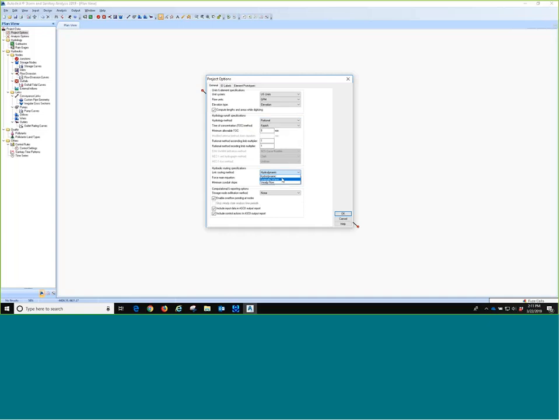So I'm not going to get into too much detail into the differences between them, but know that the hydrodynamic is actually the St. Venant equation, so it's the one we're going to use for our pressure network and our lift station design, because it's the only one that can do reverse slopes, whereas kinematic wave is just the momentum equation, and if I had reverse slopes, the results would fail out.